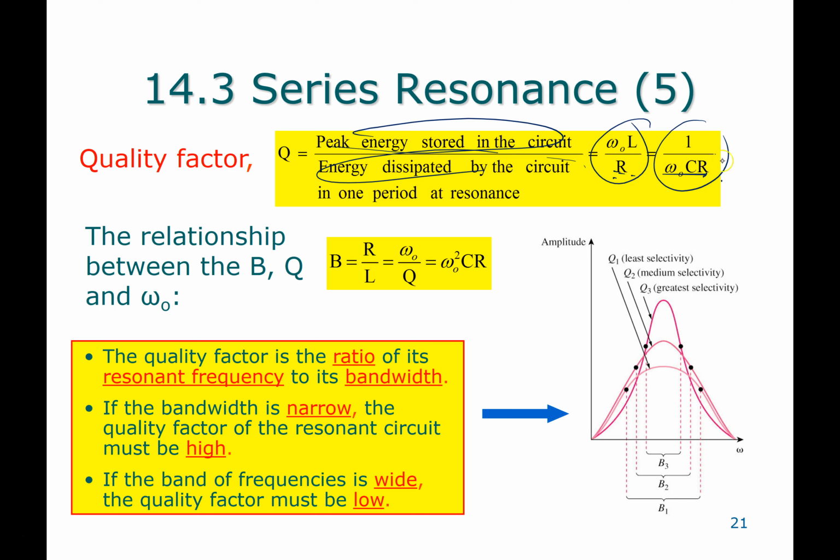Other than that, it's a little bit hard to figure out how you're going to get a big Q. But the sharper and the bigger the Q, the more selective it is, and the more magnification you get at that resonant frequency. So they're more dangerous when you're hitting right at the resonant frequency, because they're going to have really high voltages building up in them.